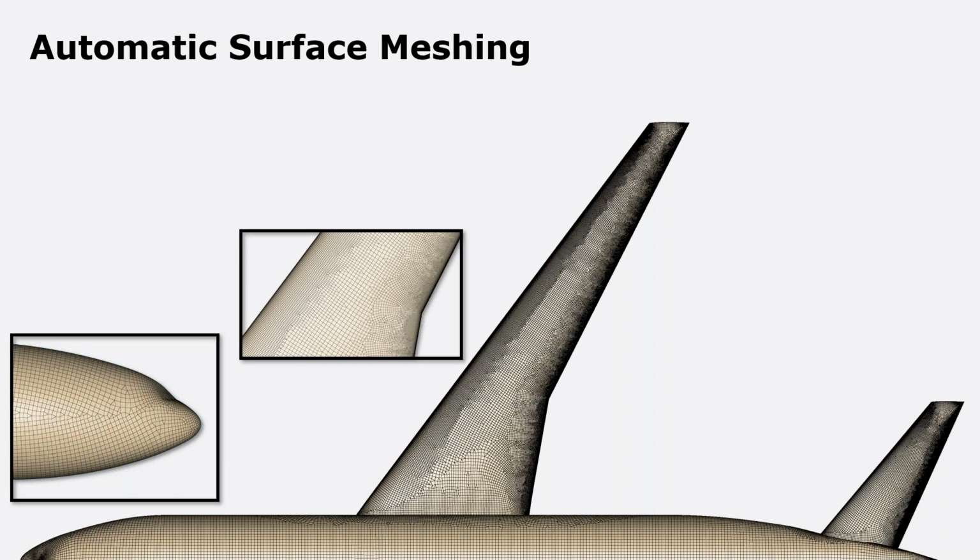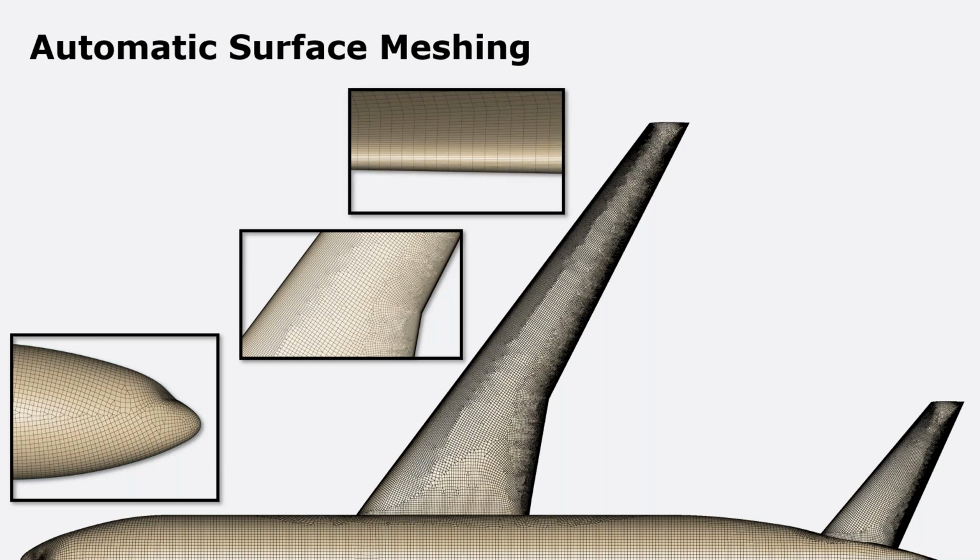You can see that if we look kind of mid-span, the transition from anisotropic stretching at the leading edge and trailing edge, blending smoothly into the interior of the wing, kind of mid-chord. We use anisotropic stretching because using this approach, we can more accurately and regularly capture areas of high curvature like the wing leading edge or the blunt trailing edge surface, those convex corners.